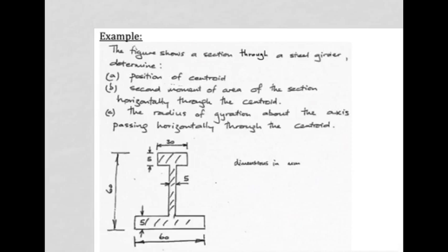Remember, as soon as it experiences bending, the fibers in the one edge will be in compression and the other edge will be in tension. And depending which direction the load is in, those might reverse. Okay, so here is our cross-sectional area, shaded, of a beam of certain length.